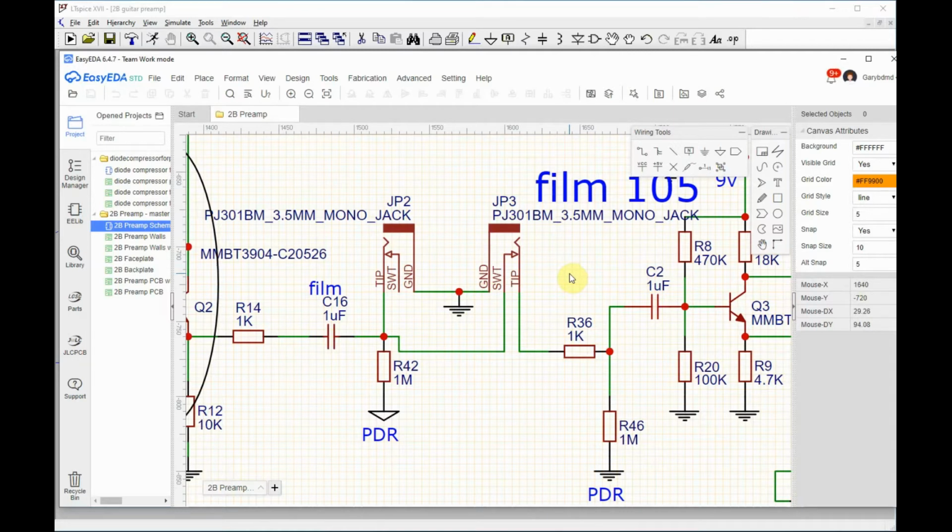The output level is usually, in my experience, like 300 millivolts or something like that. 325 millivolts RMS is sort of a nominal value, I guess they would call it. And the return is different. You would think, or at least I would think, if you're returning into something, then it ought to have a pretty high impedance input. But a lot of times they don't.